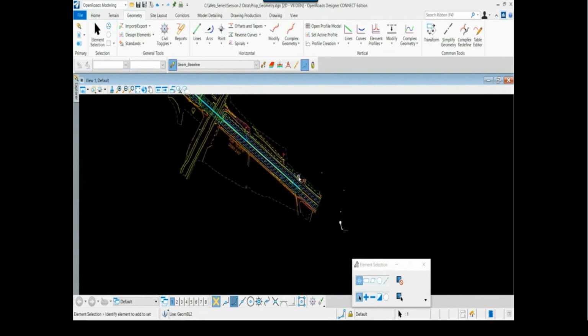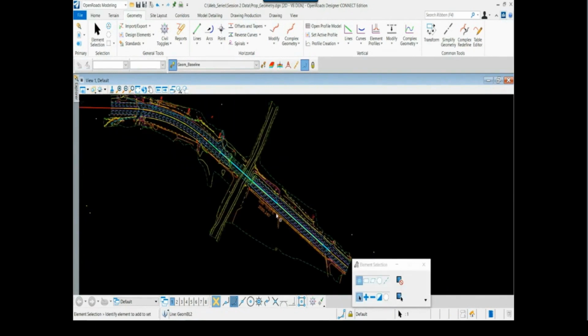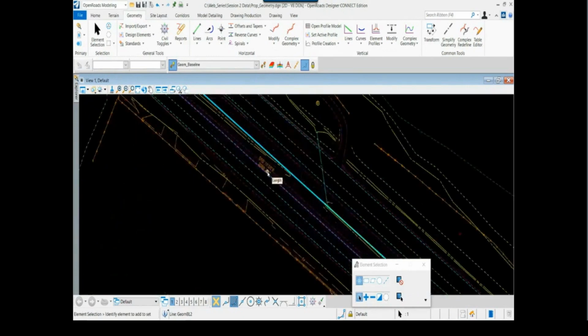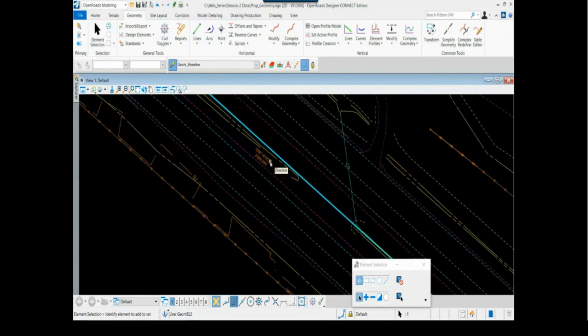Now, I will take a moment here because I want to point this out to you. As you're inputting data, as you're creating geometry, and as you're laying these elements out, it's okay if you happen to make a mistake. You key in the incorrect value for the bearing or the distance or whatever may happen. You can change that very quickly, meaning if you'll notice here, as you select that element, the dimensions, the bearing, the distance are active. I can click on either one of those dimensions directly and make a change.